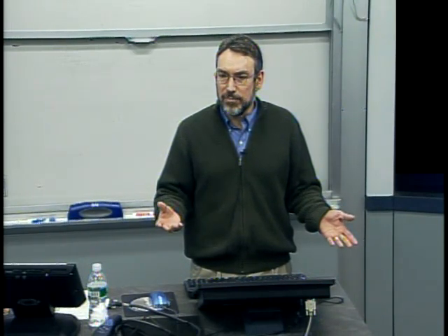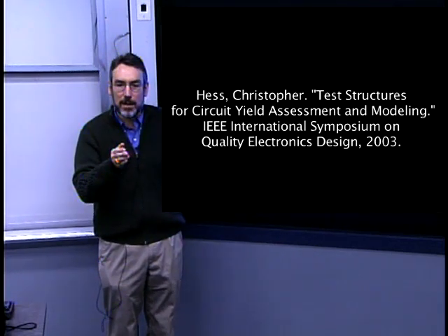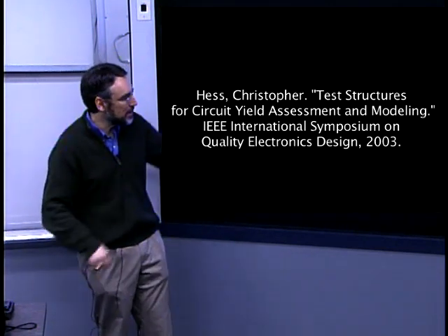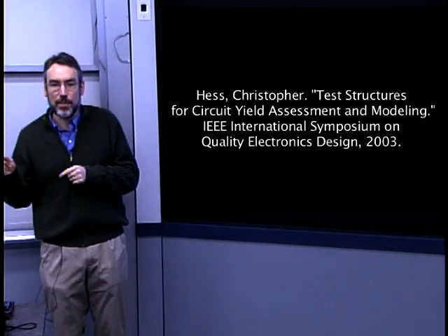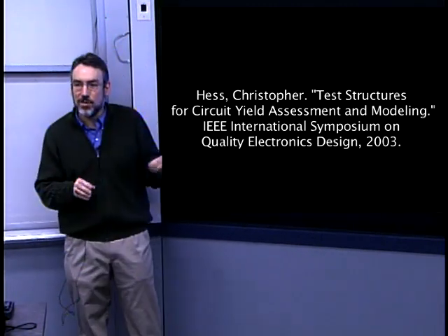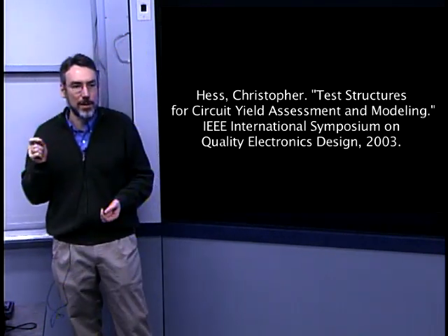Now this turns out to be still an important part of semiconductor fabrication: understanding your defect densities, defect counts, understanding what the typical sizes are, what levels of the process they come in. Are you mostly getting these in aluminum deposition? Are you mostly getting these in other etch processes? And actually then feeding that information to design for manufacturability to optimize the layout of the circuit to minimize the likelihood of a particle falling in a bad location.